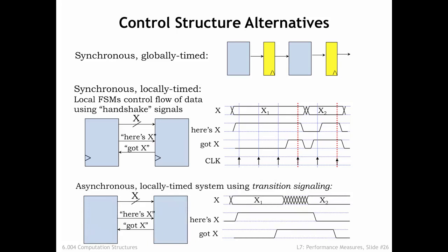It's possible, although considerably more difficult, to build a clock-free asynchronous self-timed system that uses a similar handshake protocol. The handshake involves 4 phases. In phase 1, when the upstream stage has a new output and "Got X" is deasserted, it asserts its "Here X" signal and then waits to see the downstream stage's reply on the "Got X" signal.